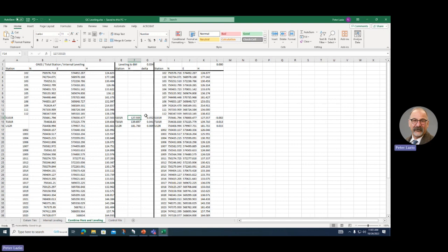By combining multiple OPUS RS, any one of them could be out a tenth or so, but when you put multiple ones together, in this case 7, we're all within a tenth. If being within a tenth of datum is good, multiple OPUS RS, or multiple OPUS for that matter, combined is going to get you there.